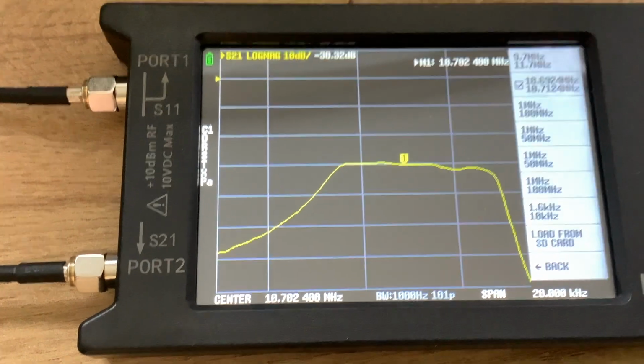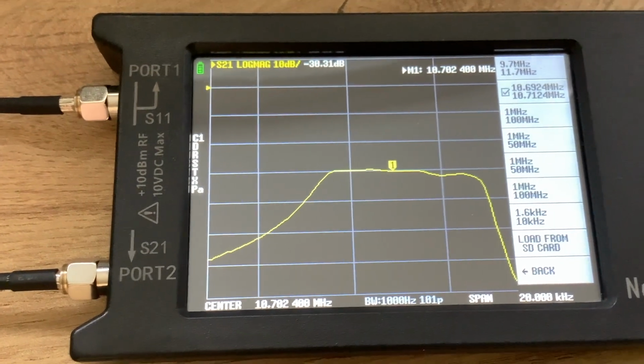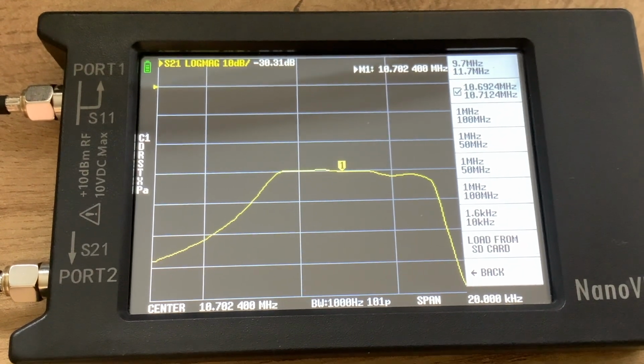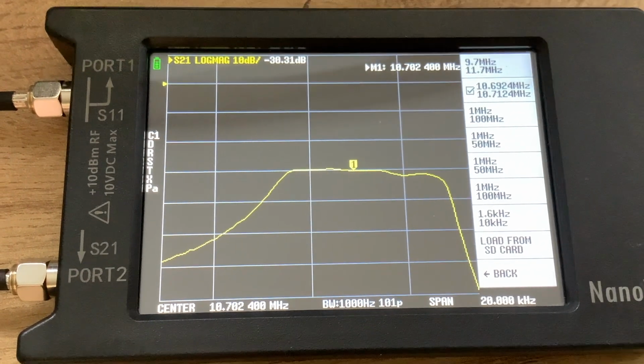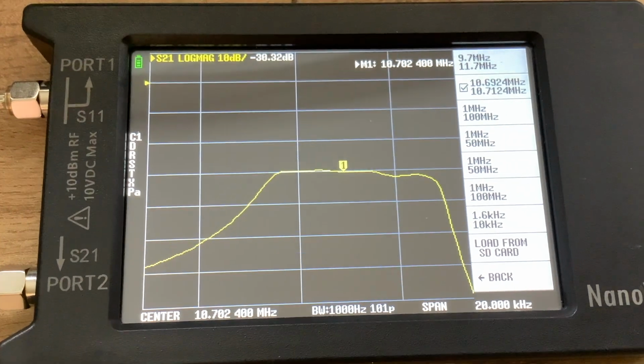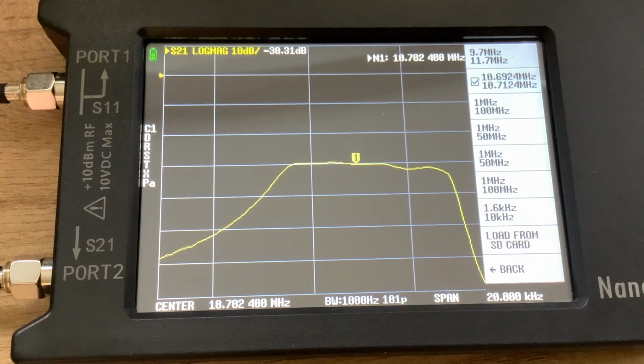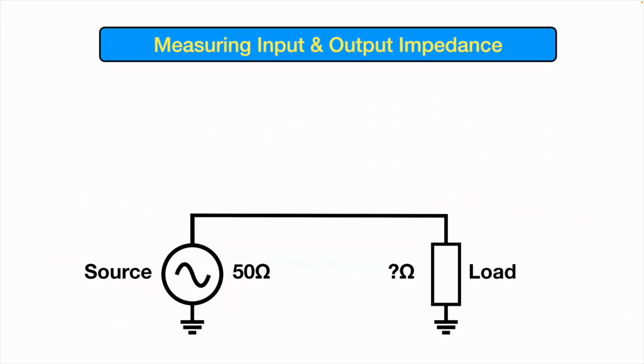And I think I'm going to shoot for about 1,200 ohms to 50 ohms, and produce something for that. And hopefully then that will give me a wider filter, which this is, with a good input and output impedance. Now, I thought I ought to just mention in a bit more detail how I'm doing this calculation, because sometimes people ask me about this.